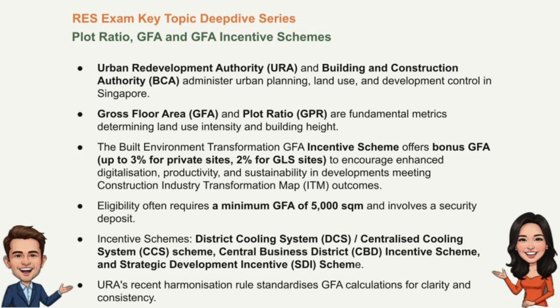Directly. There's a strong correlation. Again, these are general guidelines, but they're pretty consistent. Like, well, a GPR of 1.4 often corresponds to a maximum height of about 5 stories. A GPR of 2.8 can allow buildings up to maybe 36 stories. Wow, big difference. And if your GPR goes above 2.8, you're generally looking at permission for buildings taller than 36 stories. So high GPR often means high rise.